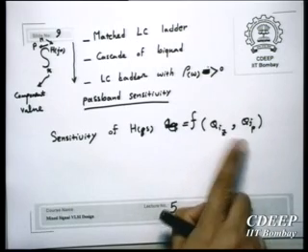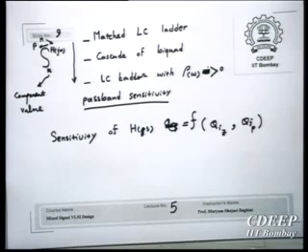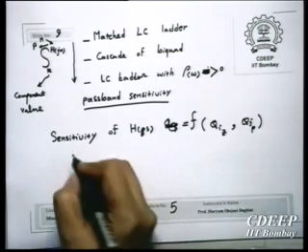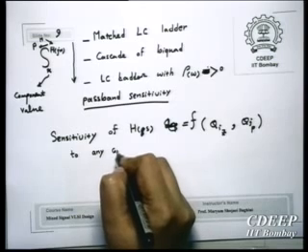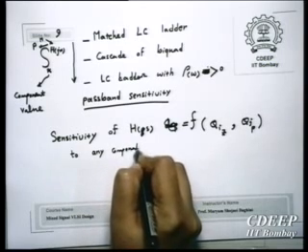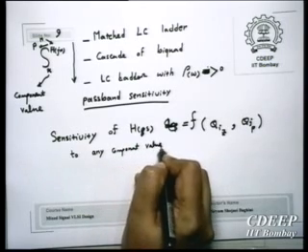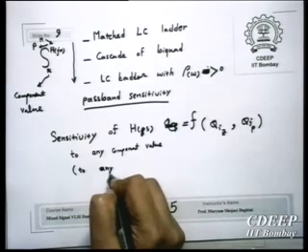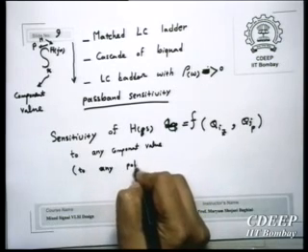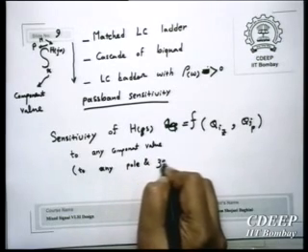If the Q of these poles and zeros is high, the sensitivity of H(s) to component values, any component value, which eventually means to any pole and zero location, will increase.